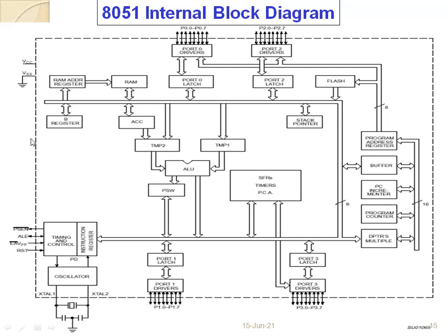You can see there is a notch over there, meaning the IC is placed in the horizontal way. So on the left-hand side of this IC we find port number 1 and port number 3, and each has the same number of pins, that is 8 pins for port 1 to port 3. Port 1 is divided into port 1.0, port 1.1, and so on up to port 1.7, so each pin is designated along with its port identity. Similarly for port 0, port 2 and port 3 also.